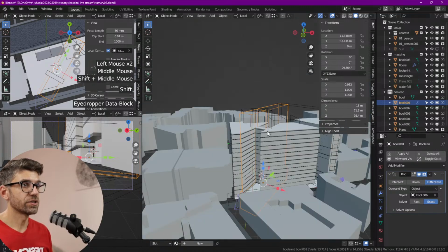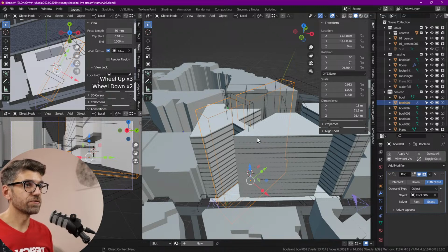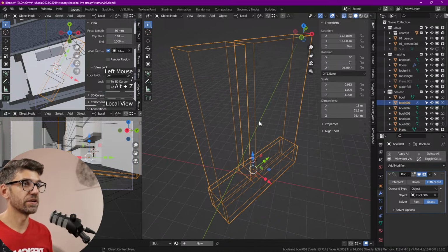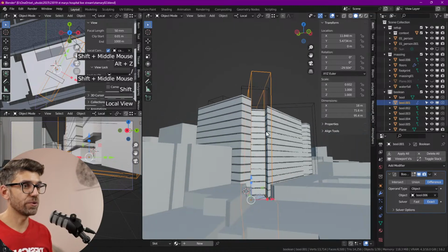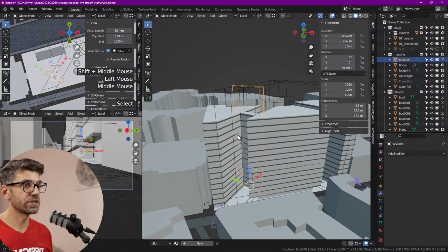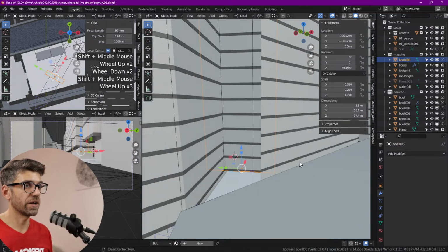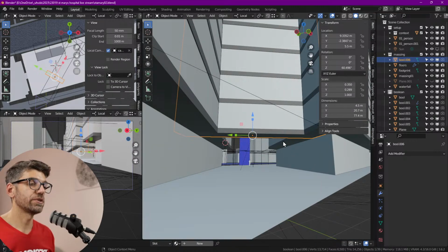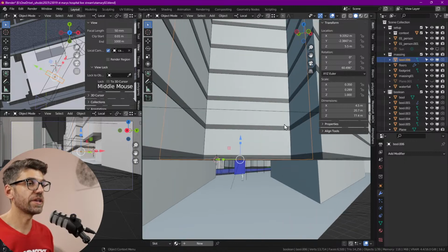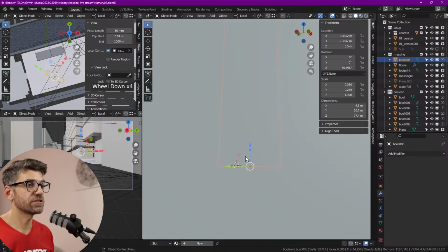And there you go. So what did we do here? We've got our Boolean box from which we're subtracting this area. So if we just isolate this, that's what it looks like, right? So we have that cut out from there, and that's allowing us to create that bridge. And we can lift that bridge because I see it's not at the right level. I thought it is. That's odd. Oh, it is. Okay. It's just 5.5 might not be enough, which is interesting. It should definitely be another level up. Or we can say that our podium is actually 2 levels.